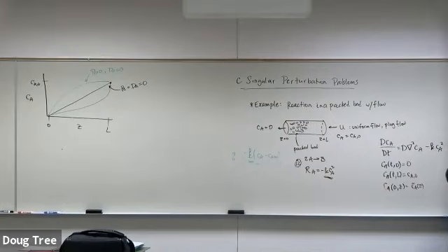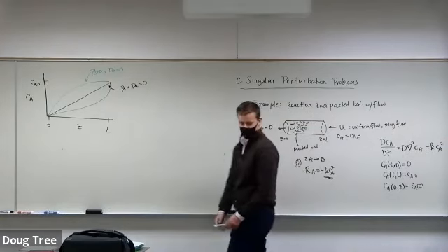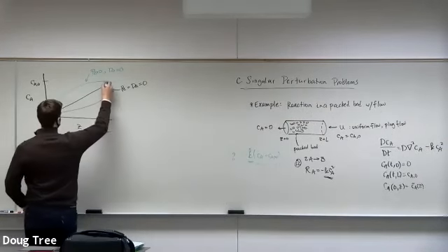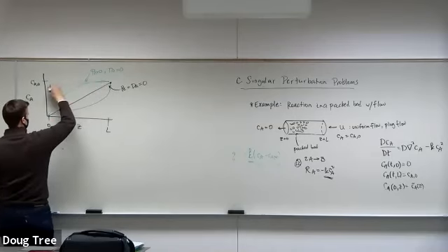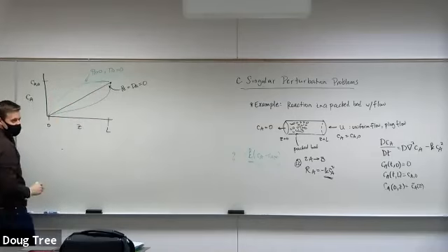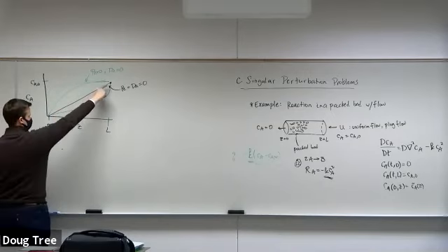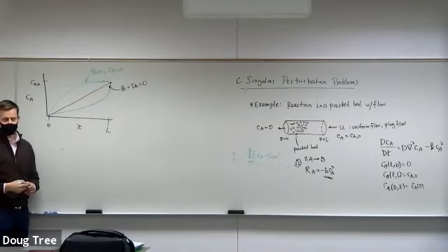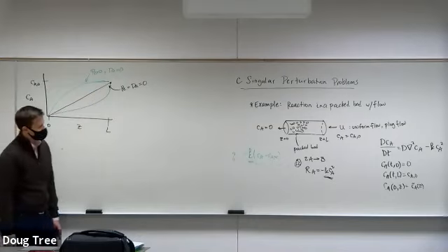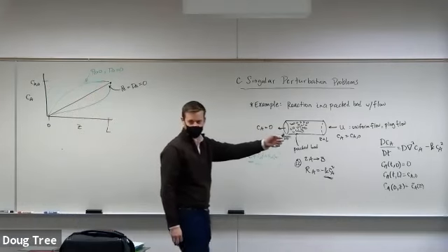Yeah, so it depends on how much convection there is relative to diffusion, right? That's what the Peclet number is. So if the Peclet number is really, really high, it's going to be more like this, or like you're saying, right? If the Peclet number goes to zero, it'll be on that line. Okay, that makes sense? Yeah, that's good thinking. Okay, so what happens with the Damkohler number then? What's the Damkohler number doing?